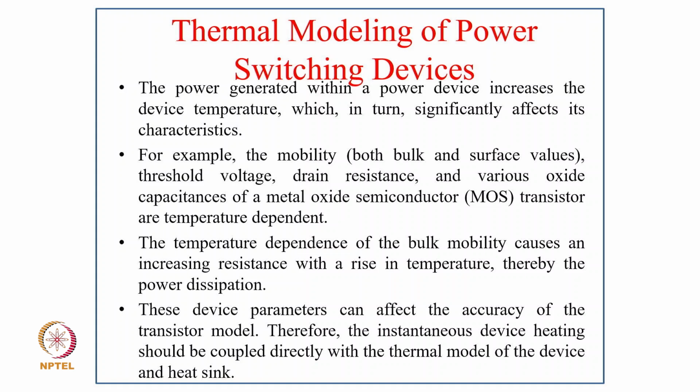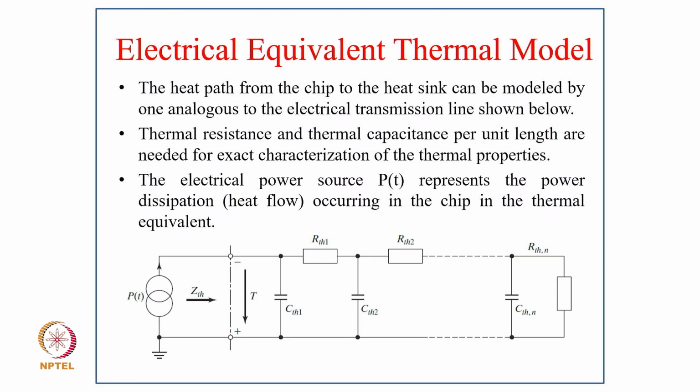Therefore, the instantaneous device heating should be coupled directly with the thermal model of the device. Coming to the electrical equivalent thermal model of the complete heat sink, the heat path from the chip to the heat sink can be modeled by one analogous to the electrical transmission line shown here. Thermal resistance and thermal capacitance per unit length are needed for characterization of the thermal property.